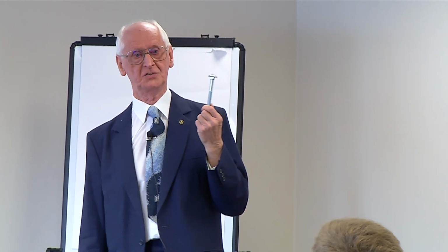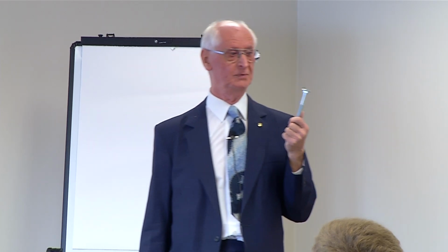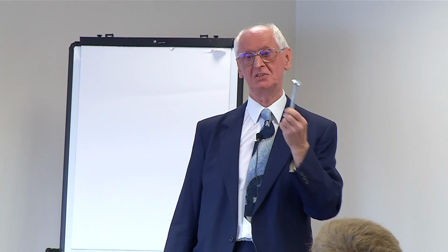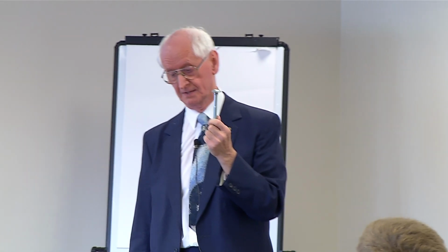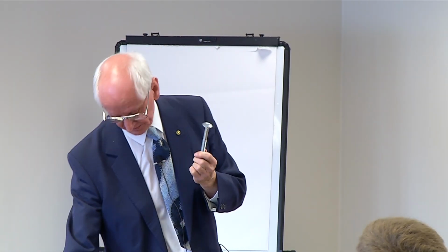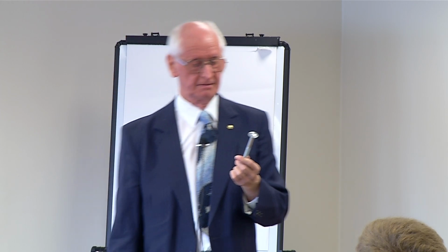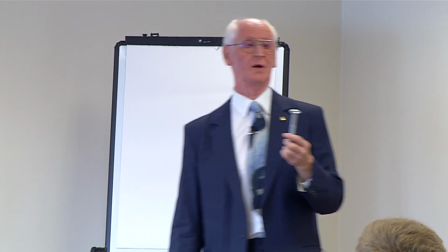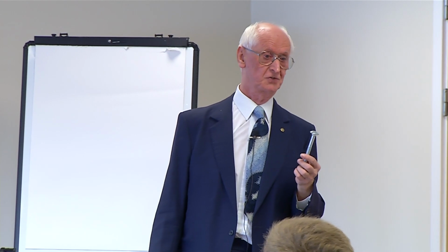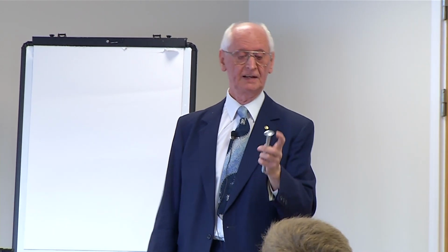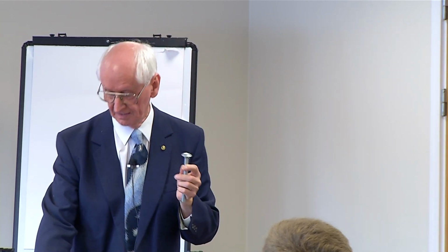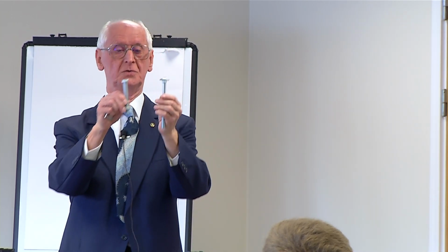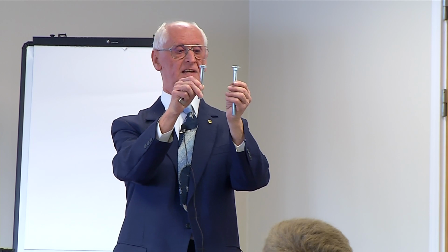These things are too commonly available. They are misused by builders on an industrial scale, and they have a load of problems. First of all, they don't comply with the standard that we want for the strength. Secondly, the head, as you can see, is quite rounded. It hasn't got the strength that you can see in a hex head bolt.